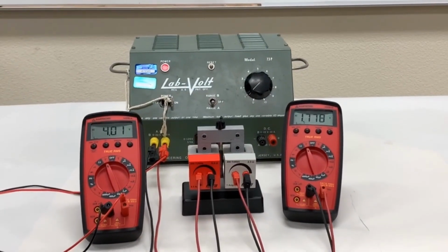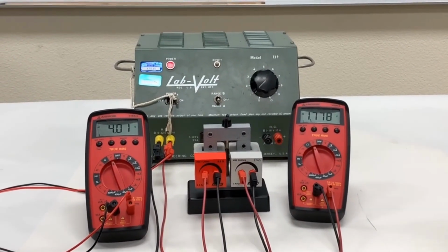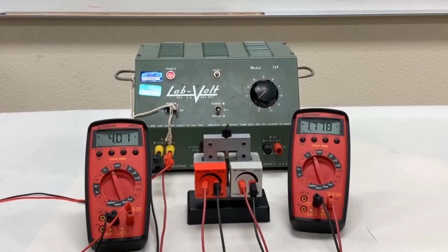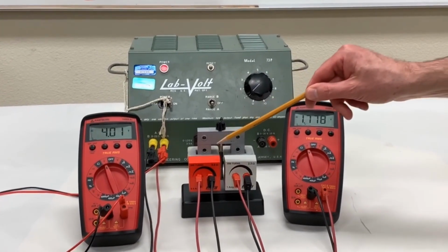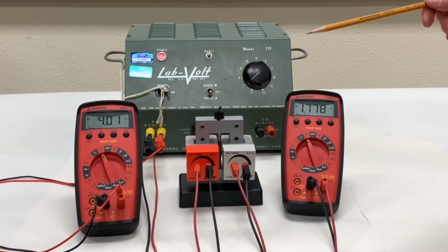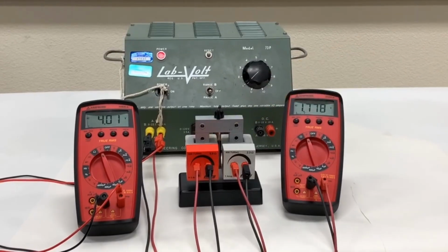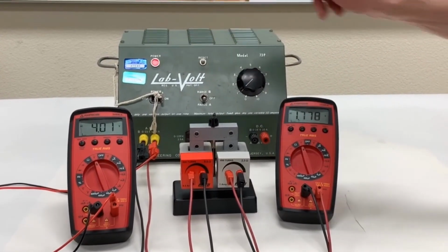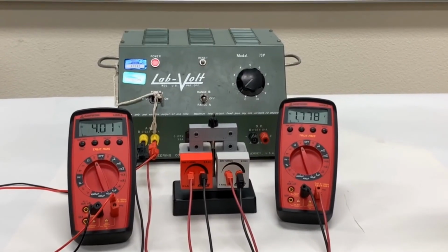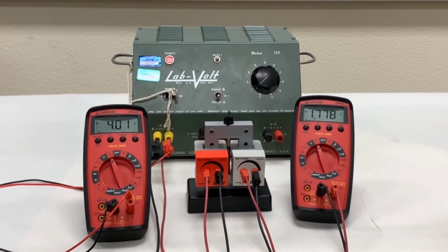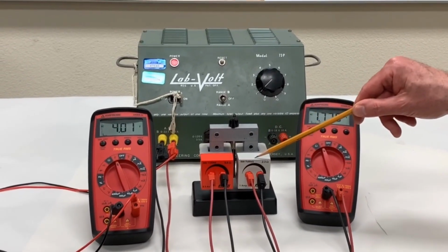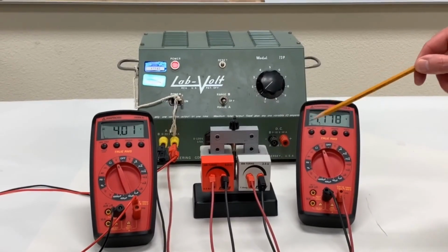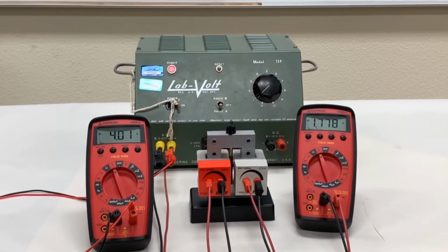Now you'll notice in this setup, if you're very observant, that we have interchanged the two coils. So you'll notice that the red coil on the left, which has a greater number of turns, the 800 turn coil, is now connected to our power source over here. It becomes the primary coil, whereas the coil with a fewer number of turns, our 400 turn coil over here, is now our secondary coil, providing us an output voltage.